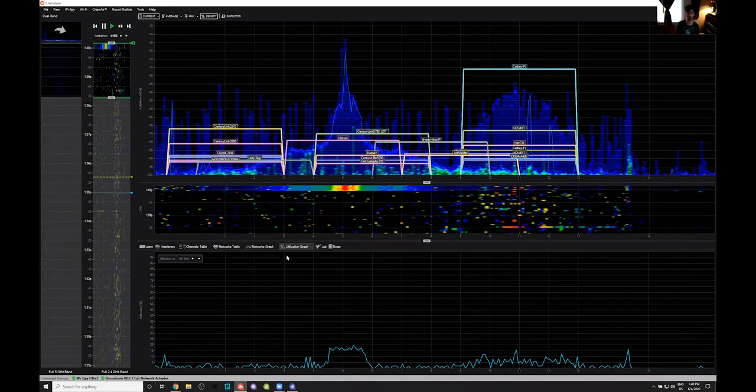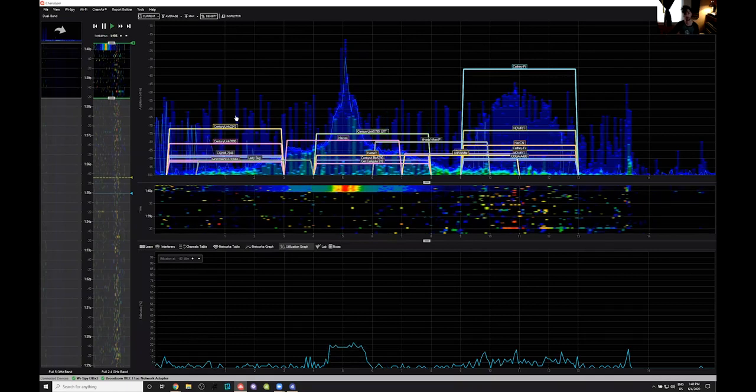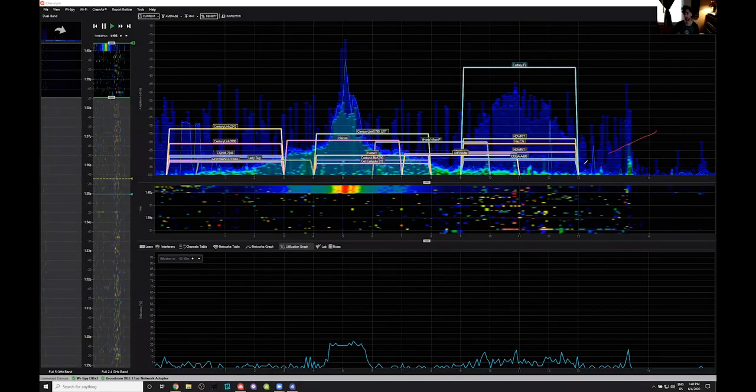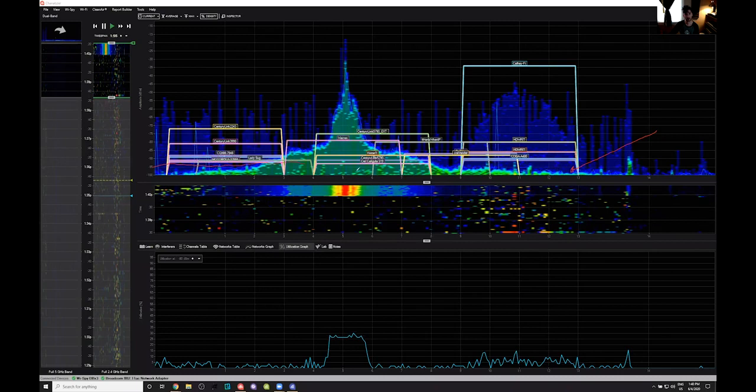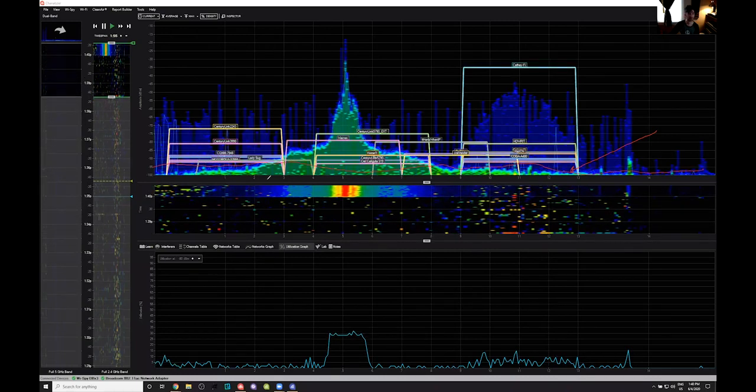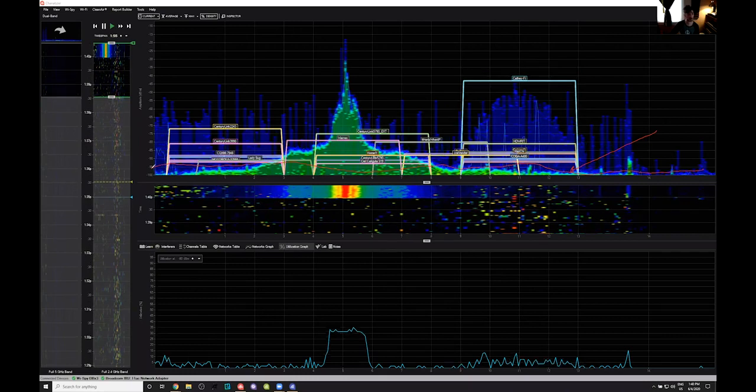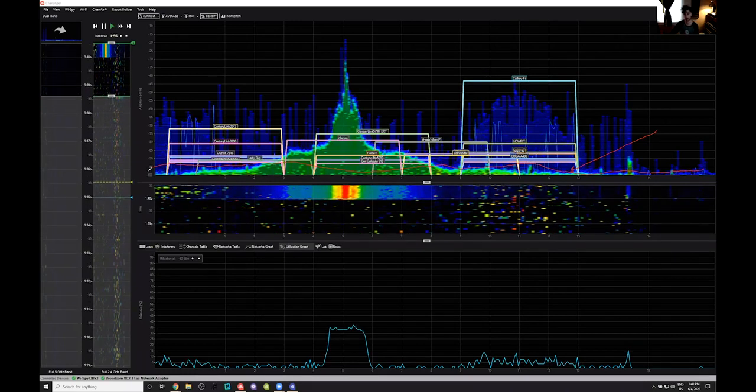When I introduce this interference, you'll see the noise start to populate a bit more, at about negative 95 dBm is about my noise floor here. There really isn't much of a noise floor other than that. It's at about negative 100. So my Wi-Fi environment is actually pretty clean here.